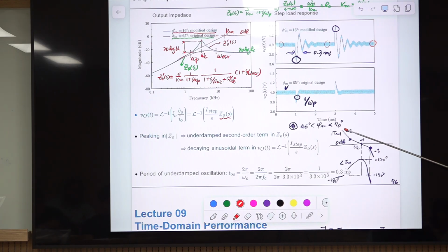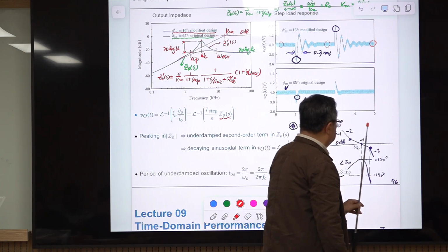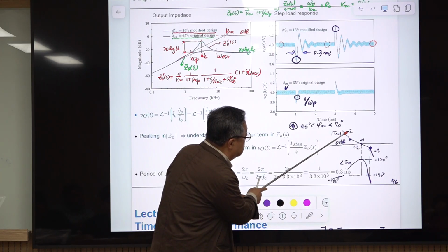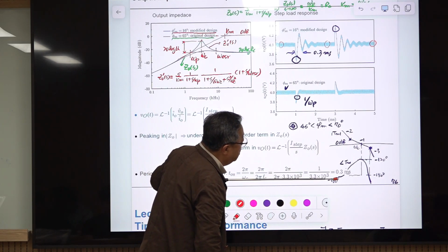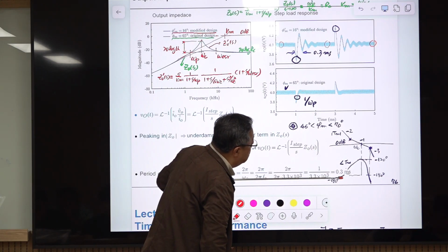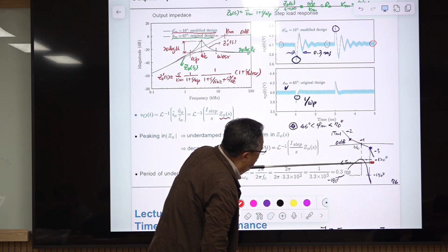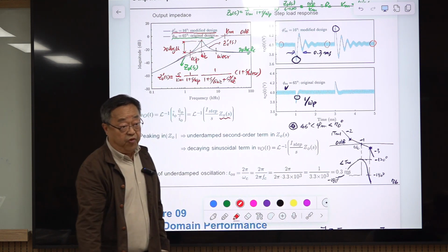Another important thing is to consider this one. This is the loop gain plot, asymptotic plot. The phase of this is -2, and there is a 1, 0. So the phase changes to this minus 1 slope, and there is a double pole here. So the phase becomes -1, -3. Maybe you think this is good because you have good phase margin here. So this was -2. The slope is -180 degrees, and with this the phase will increase toward -90 degrees, but in the middle you have this point, so you have 60 degrees of phase margin.